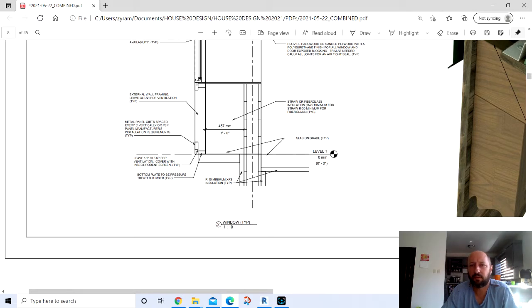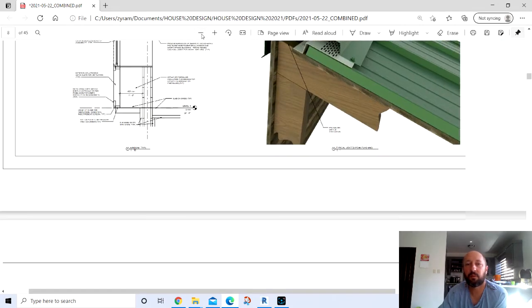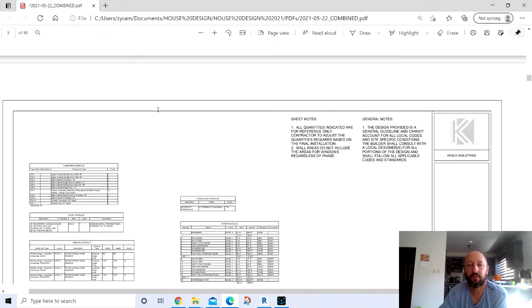One way, I don't know if I mentioned, is changing out from straw to fiberglass. That's not only a cost savings measure, but also maybe feasibility. If you don't have inexpensive, good quality straw readily available, then reducing that cavity and changing to fiberglass insulation would be a possible positive change to make. It would reduce the cost. You might reduce the cost several $1,000s. So I'll probably look into that when it comes time to build.